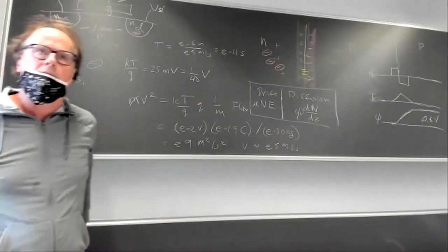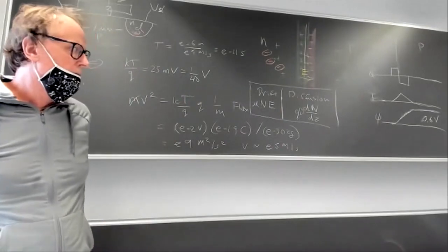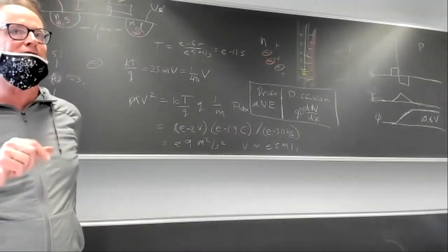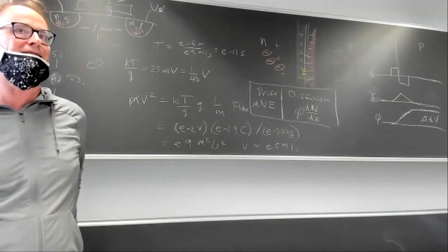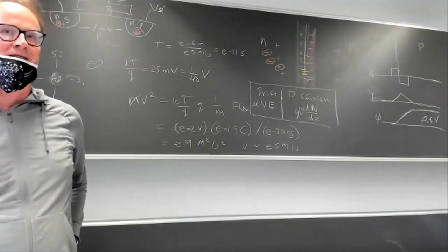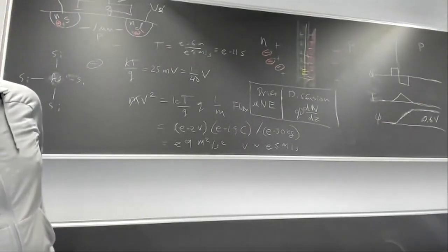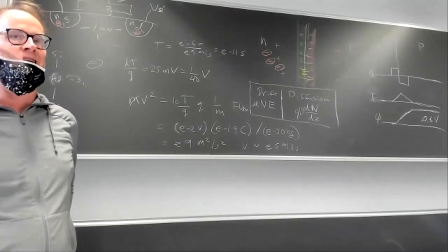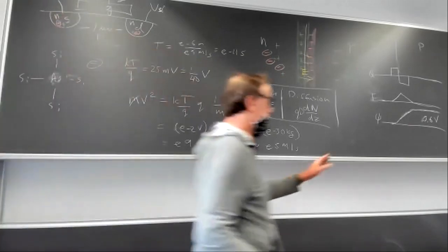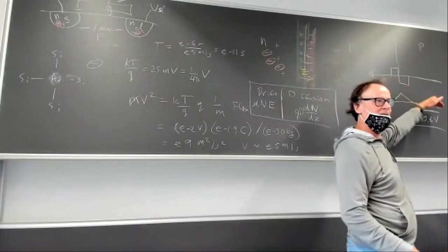Yeah. So when you're actually connecting a diode to a voltage source, it goes P first, right? So shouldn't the potential be flipped the other way? It's very confusing. This is the potential energy for electrons. Okay. Somebody made a mistake and made electrons negative in the beginning. And that caused endless confusion since then. But it's a potential energy for electrons. You don't worry about that sign, right? If you don't get consumed by worrying about the sign here. It just means that you can think of a potential energy for electron. You have to do work on the electron to make it climb up this barrier.